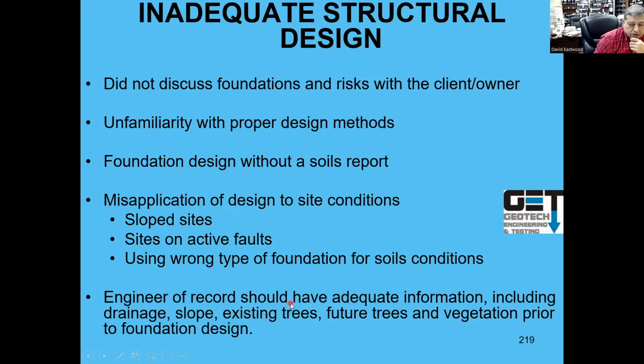The engineer of record, who is the structural engineer in this case, should have adequate information including drainage, slopes, existing trees, future trees, and vegetation prior to foundation design. Somebody was telling me the other day, soil reports are only recommendations. The structural engineer who seals the drawings is the one who is actually doing the design. So I don't know, it's more liability for structural guys.